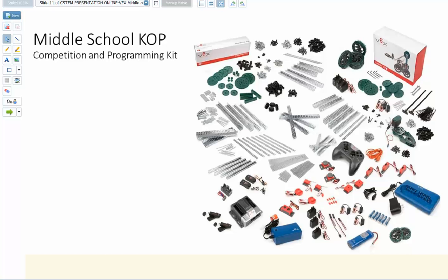This looks like a 9-volt little case. That's what it is. This is actually a battery backup. When this battery runs out during competition, because your kids forgot to recharge it between competitions, you pop in a 9-volt battery, and it goes onto the microcontroller. It still receives signals. It doesn't allow the controller to burn, and it should allow you to continue running some of the motors, etc., if you still have a charge on your controller. So very important as a backup. It's a backup battery resource.